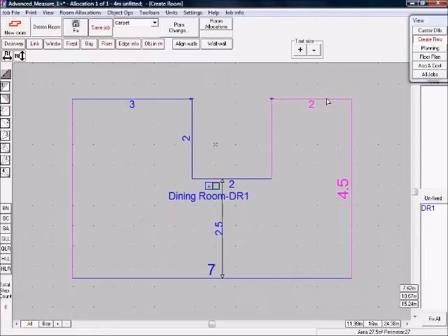By deducing all the dimensions that can be deduced, the space you draw is always a valid shape. Having a record of which dimensions you have entered is also valuable because you can use the pink deduced ones as check measurements. Some systems don't have this scheme, and on these systems, when you amend a dimension, it may alter another dimension that you have input, i.e. a blue one. But you don't realise this and a mistake can result. With this system, the only dimensions that can alter without you saying so are pink ones, so you know where you stand.